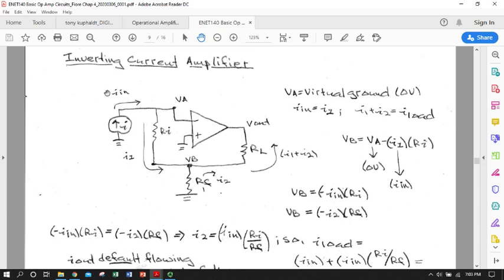So here this time we have a current source. Remember the characteristics of ideal current sources. They will give you whatever current you need and will exact whatever voltage they need to give it to you. They have high, if not infinite, impedance. And the symbol is a circle with an I and an arrow indicating the direction of conventional current. So we have some voltage rise from ground, whatever is necessary for our current source to give us whatever current we have. And that's defining an I in to this node.